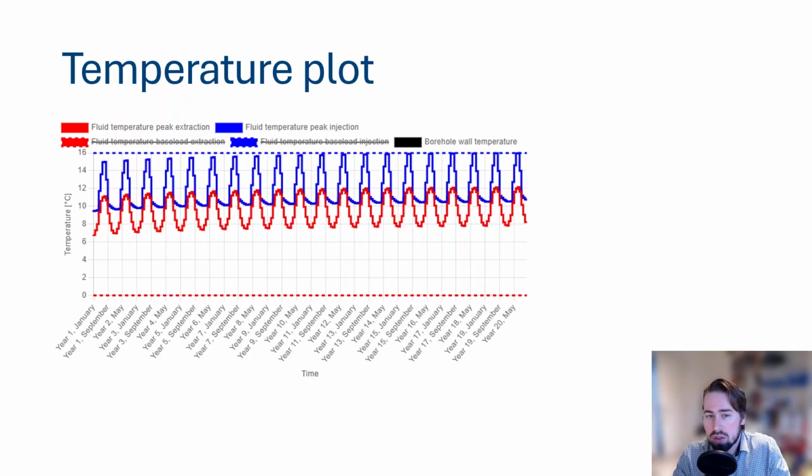Now, of course, we can also have this situation where we again have a limitation by the maximum average fluid temperature, but now our Borefield heats up year after year. So in our climate zone, that can, for example, be an office building, which typically has a lot of internal gains. But if we also place a data center in this office building, we can more or less be sure that we have more cooling than heating demand. So here the imbalance is the other way around, heating up the ground year after year.